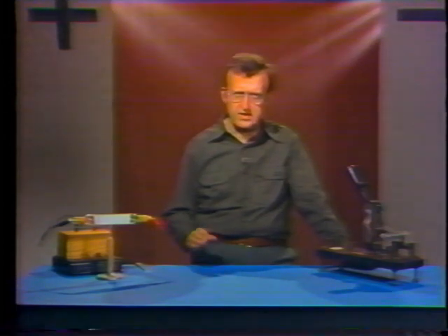As the distance between the contact points increases, the resistance of the air gap between them also increases. From Ohm's law, you know that increased resistance means decreased current. So, as the resistance of the air increases, the current flow that's keeping the arc going decreases. When the resistance gets so high that current can no longer flow, the arc stops.